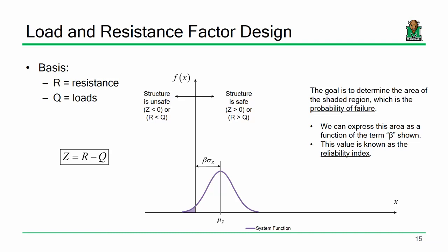The loads are things like dead load, snow load, wind load, earthquakes. For each of those types of loads, we apply load factors to address their specific uncertainties. Same thing with resistance. We apply different resistance factors to elements experiencing compression versus tension versus bending versus shear. Each one of those has a particular resistance factor. The long and short of what we're trying to do is address uncertainty.